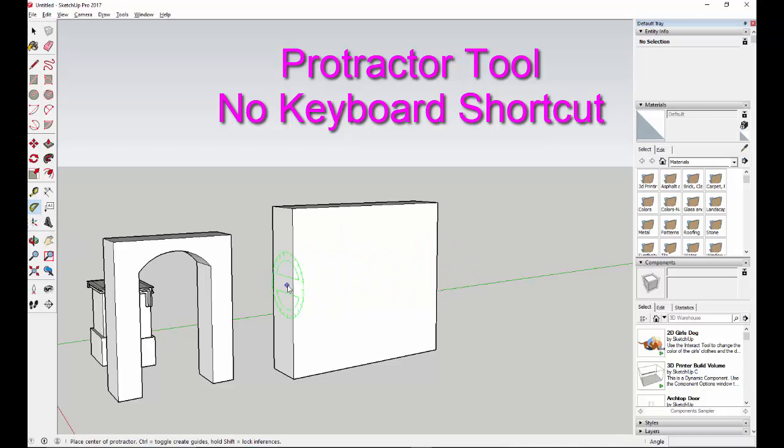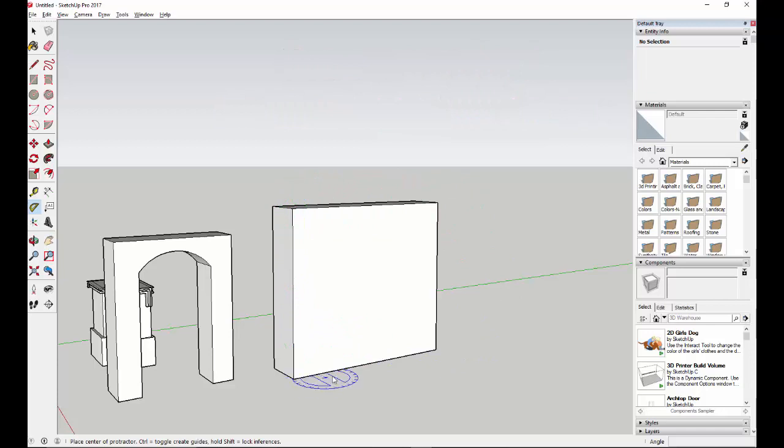And it's a lot like the rotate. You have to first select what axis you want to work with and where you want to start your guideline. So I'm actually going to start in the corner, and I have to give it a reference line to work with. So see how I'm going parallel here? Reference line, and then I get to tell it what angle I want it to go at. Now if I want a 45-degree angle, I could type 45 or find 45. I'm going to do 60, just like that, and it places the guideline at an angle.